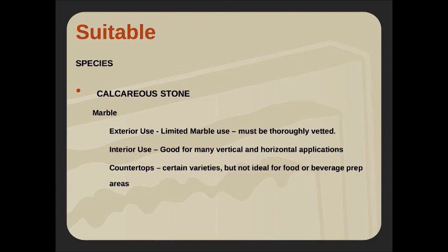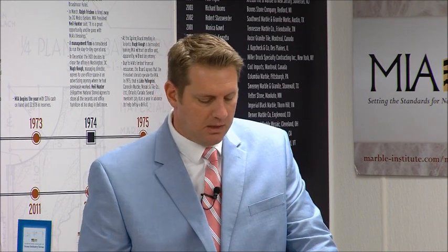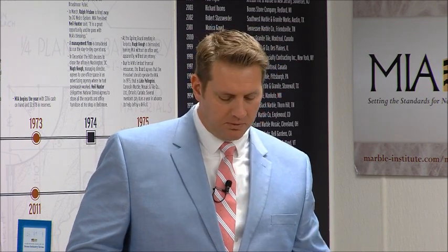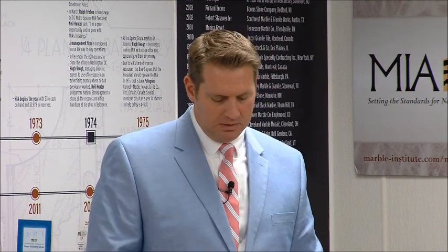I think the key with the marble is we got to ask ourselves, is it an A, B, C, or D in soundness? And if it's the C's and D's and the factory is requiring the resin mesh reinforcing on the back, let's make sure we've asked that question early on, so that none of us are surprised after the bid when we find out that the installer didn't have epoxy thinset in his number, and then we're battling that. So it's just important to know what the classification of the marble is, so that we are prepared and we're specifying the appropriate setting method.